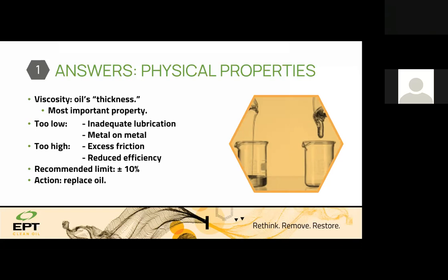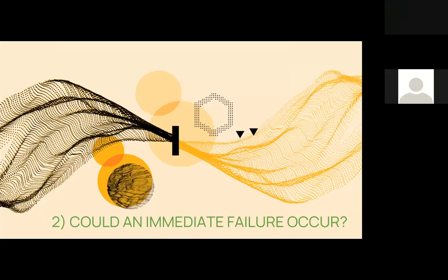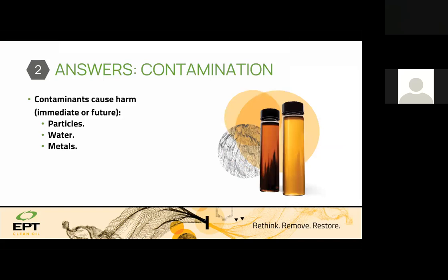When we are talking about turbo machinery, which is mostly ISO 32, it means plus and minus 3.2 centistokes, and for an ISO VG 46 it is 4.6. So it's very clear-cut to do the analysis of viscosity. Generally viscosity changes, if there is no problem of a wrong lubricant being added as a top-up, then you need to look at the end of life of the lubricant when the viscosity is going high. And then let's focus on whether there will be any issues on the way.